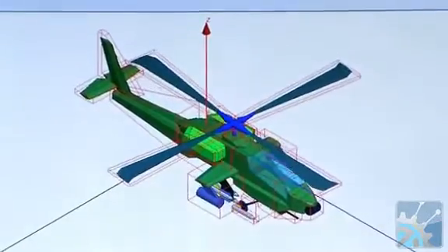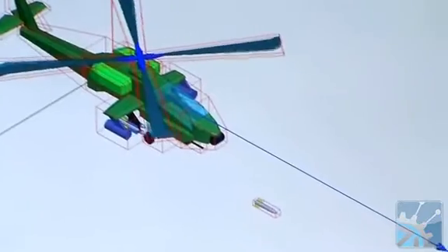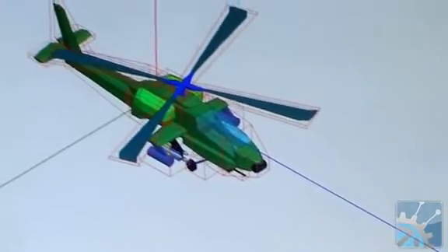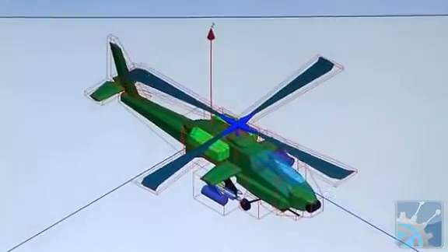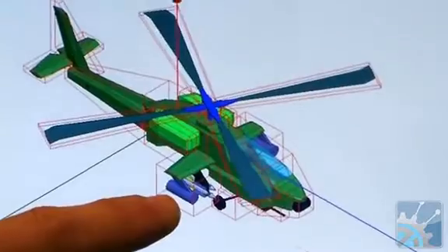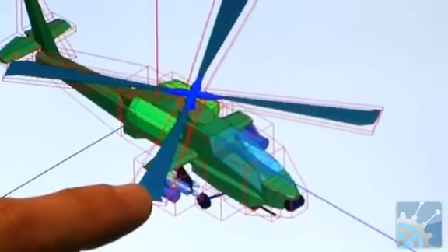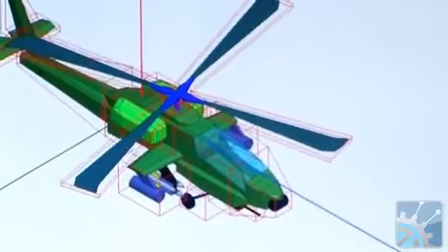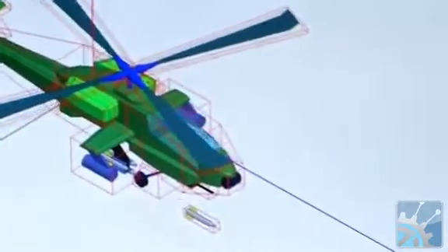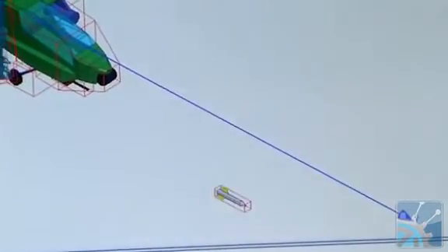It's very efficient, extremely accurate. It's a very accurate solution to the free space Green's function using finite elements. One other interesting aspect that this animation shows is you can have physically separate domains. In this case, if you watch the animation, you'll see that a missile launches out of the helicopter, and that missile itself has one of these conformal air volumes surrounding it. And this is all encapsulated in one single simulation.